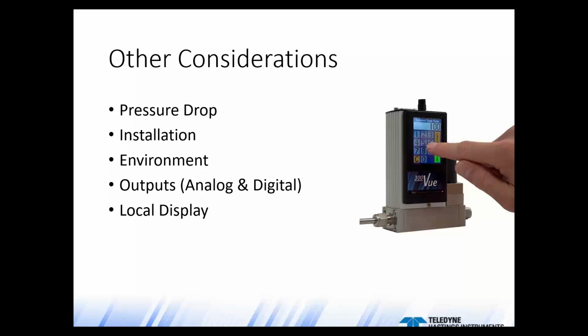For example, our LFEs, those laminar flow elements that I showed a couple slides ago, have only corrugated matrix passageways and offer minimal resistance to flow. Now, of course, LFEs should be installed properly with a nice long straight run of pipe. We usually recommend 5 times the diameter of the pipe upstream of the flow meter, and additional straight run of pipe, say 1x to 3x diameter on the downstream side.